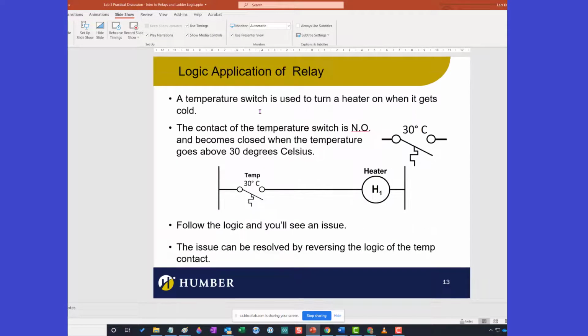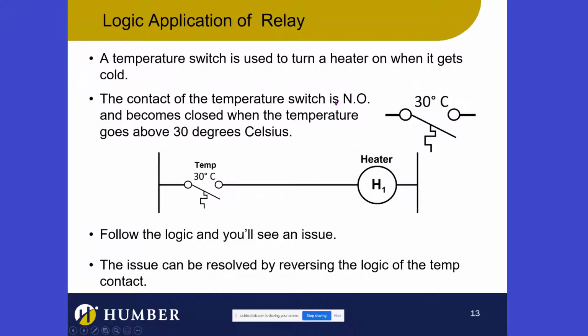Okay, so let's go here. Let's continue on here. So here we go. The contact of the temperature switch is normally open, and it becomes closed when the temperature goes above 30 degrees. Okay, good. So this is the problem. This will close when it goes above 30 degrees.